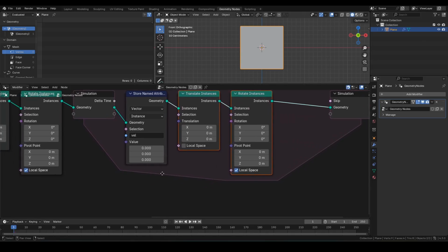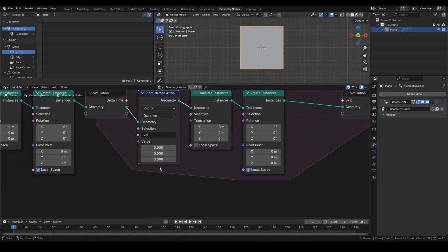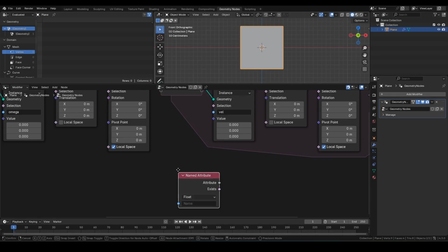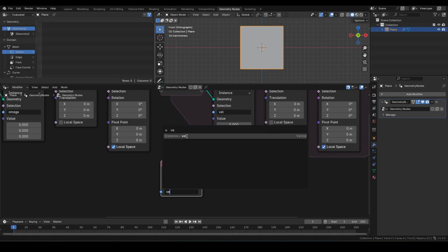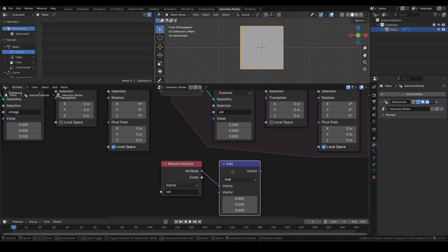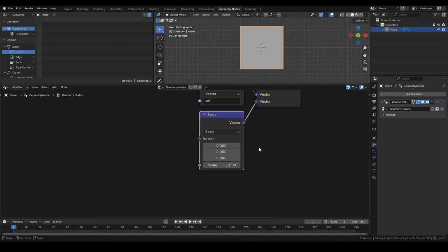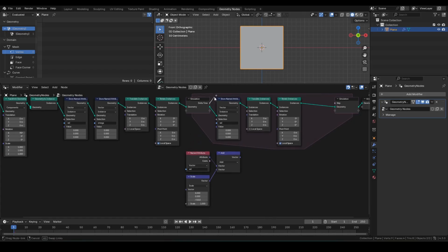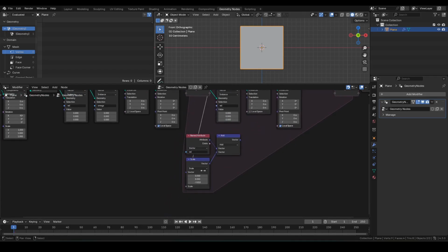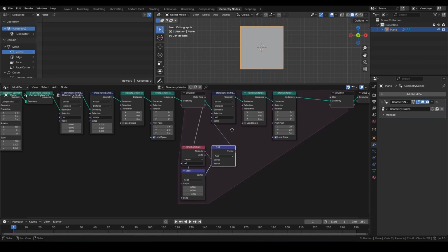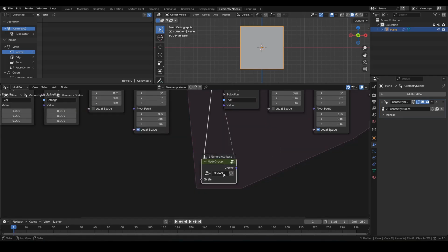We'll first start with the velocity. Add a named attribute vel. Connect to vector mass add. Then connect the vector mass scale to bottom socket. Enter the gravitational acceleration of negative 9.81 to z. Then connect delta time to scale. Use the add result as vel for current frame. Select these 3 nodes and Ctrl G to group. Tab out and rename to calc vel ff. ff for freefall.